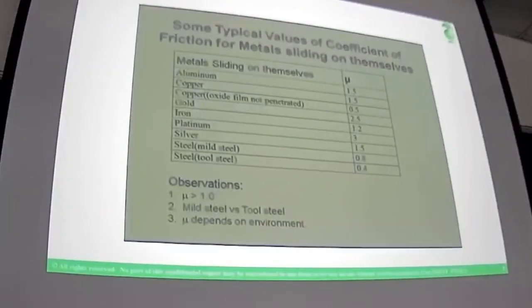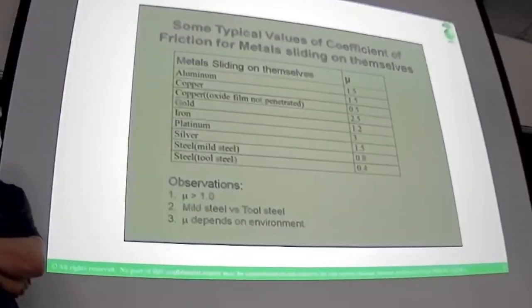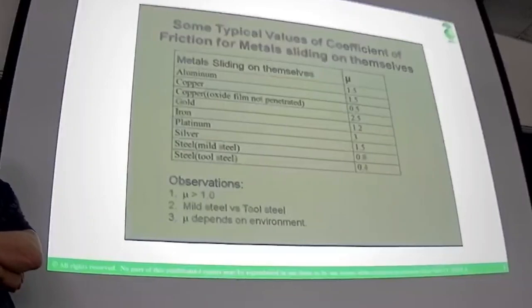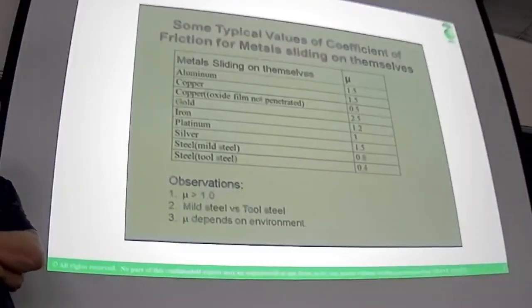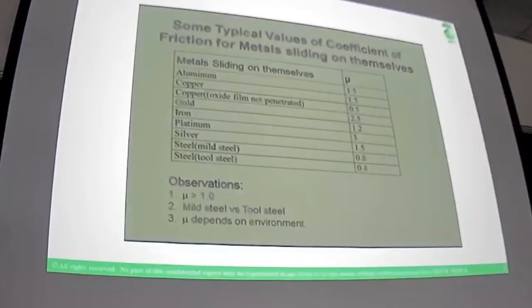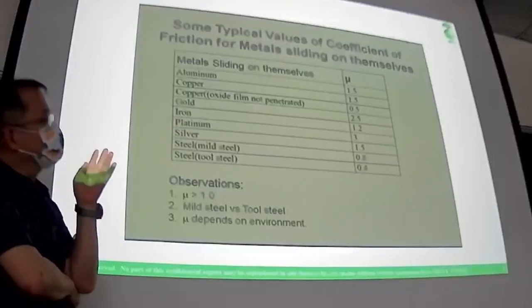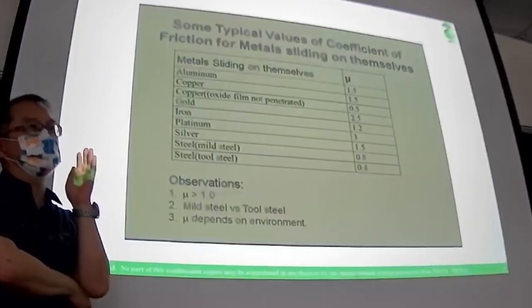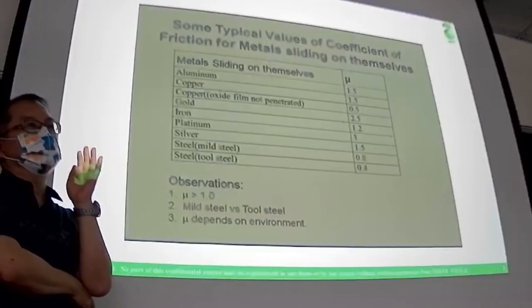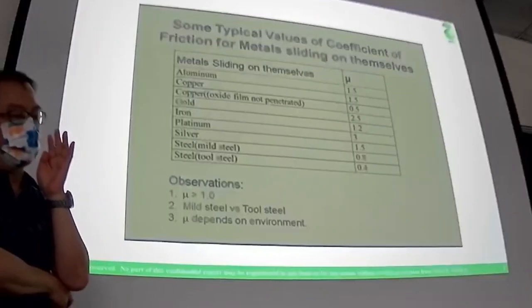So we have already given you a brief introduction from the Tribology 101 PowerPoint from Bruker. Okay. So we know friction is a system property. You cannot say that one material has a coefficient of friction. You need to give a clear explanation of the counterpart.